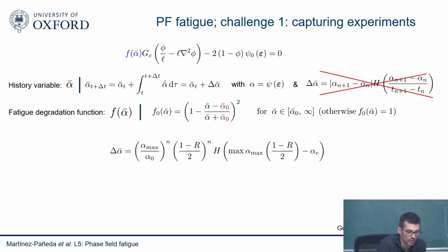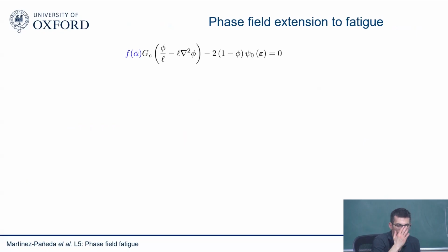I mean, it's a choice. So we have a driving force, and you have a fracture resistance, toughness, and accumulation of your driving force for fracture, stored energy. Some people have argued in the phase field fatigue community that it's a little bit the same as in the phase field ductile fracture community. So there have been 2 approaches. Some people say, I want to enhance my driving force, I want to maybe increase this with the number of cycles, or I'm going to degrade my fracture resistance.